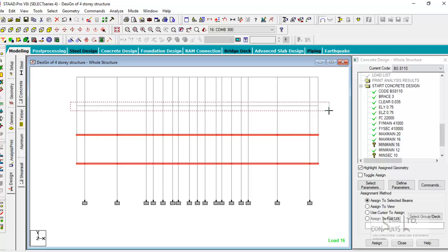One would want to ask why we are looking at T12 as the minimum size of reinforcement on the columns. Note that columns are predominantly carrying concentrated loads. And if you look at the equation for column design under axial loads, you have that the design load N is 0.35 FCU AC, where AC is the area of the concrete cross section. Then plus, if you take into consideration the fact that you have holes in the concrete cross section, you will subtract the holes of the reinforcement, which is 0.65 FCU area of concrete plus 0.75 FY minus 0.35 FCU area of steel.